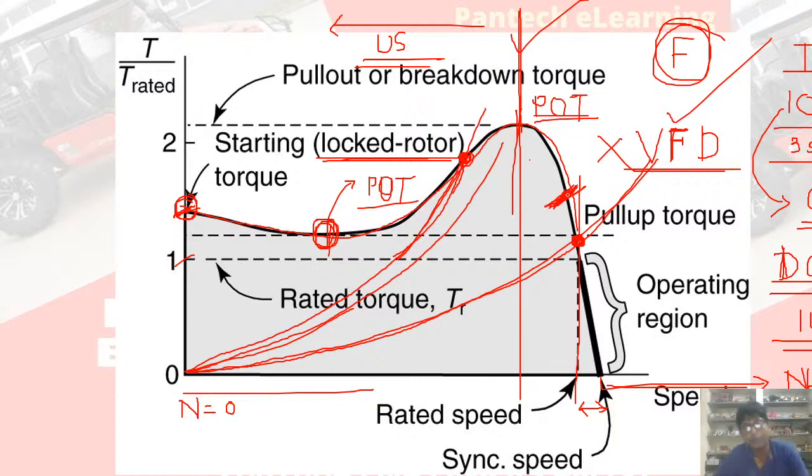Okay, so sorry, my required torque, so here this is my operating point, and due to some transient condition my machine shifted here, away from the operating point. Now my available torque is higher than the required torque. If that happens, my torque is more, so it will run faster. It will run faster to catch this point. It will come and settle down here.